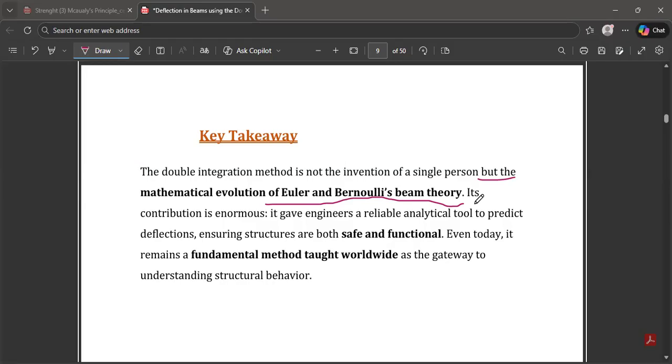You first take all the beams and calculate the shear force and bending moment. Also, you calculate the deflection to check whether the beam is safe. You have to analyze the structure very well. You also take the columns and do all your load calculations. In our lecture 5 or 6, we are going to be doing column calculations, and you will see how to apply some of these methods. So it's very important.